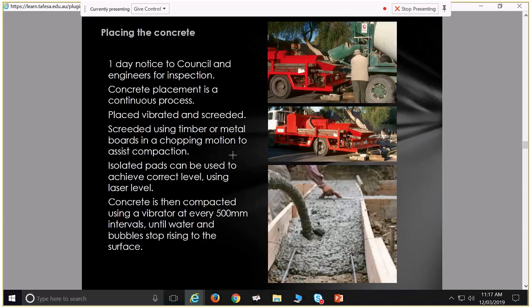If the concrete's not rocking up as it's meant to be, well then that's on the supplier. So you're not going to be paying that bill. But yeah, of course, there are various case-specific things. But as designers, you have to understand these things. You have to understand that essentially the concrete does have to happen as a continuous pour. If it's not happening as a continuous pour, then you have construction joints. Those construction joints are going to be articulation joints in the building, etc. And that has to be catered for throughout.